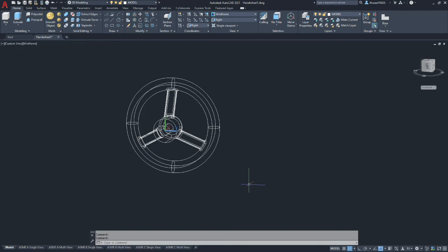And that's for clarifying the section view so that we have clarity on what we're sectioning, what we're trying to describe in that view. What we're trying to describe in that view is the geometry that makes up the side profile of the hub and what the cross section of the hand wheel appears like.